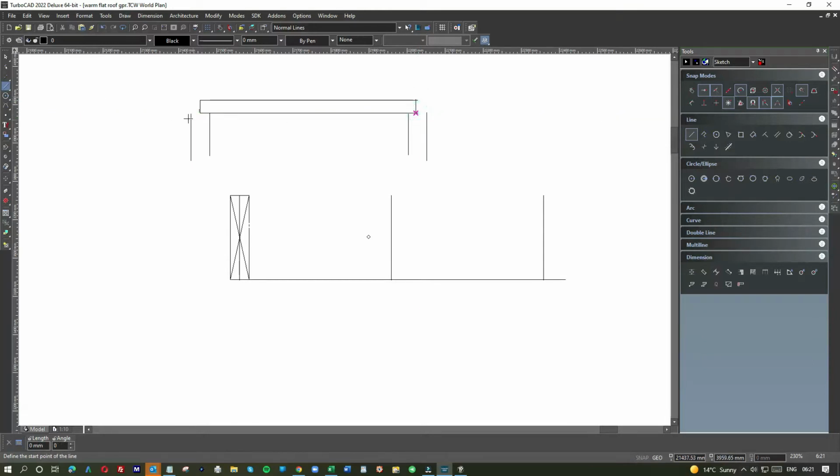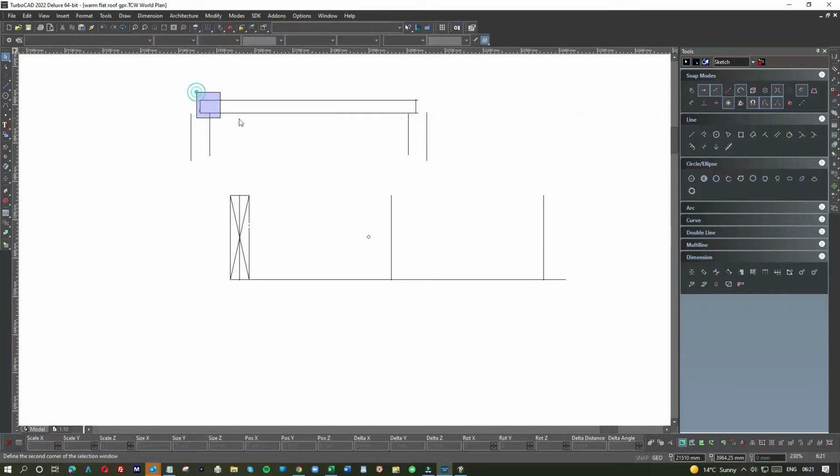So if those were your side walls and this was 12 foot, the general rule the engineers used to use for imperial, I was taught this when I was quite young, is half plus 1. So if it's 12 foot wide, half is 6, then plus 1, 7. So we would actually end up using a 7-inch beam here.